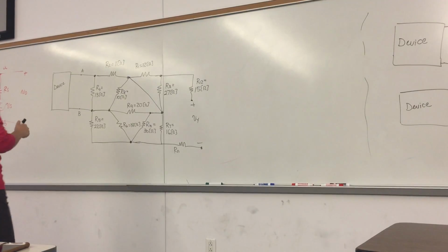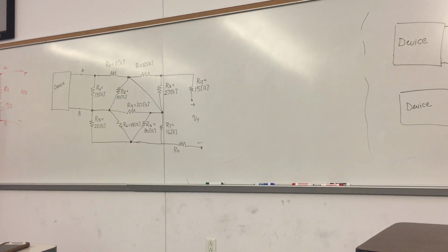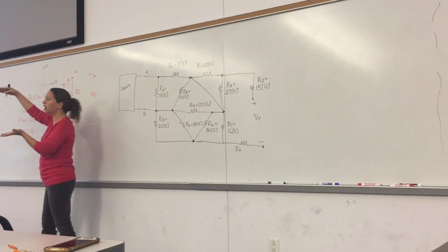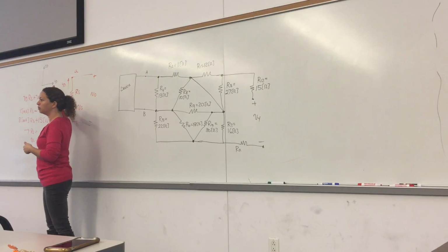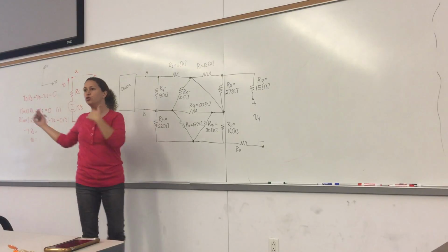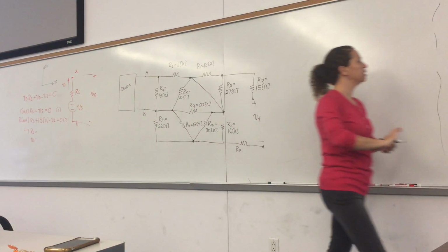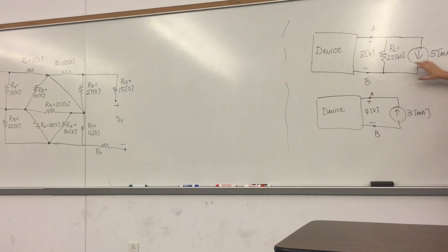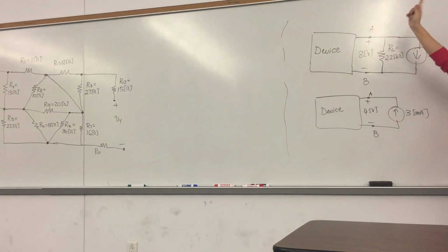Normally in those graphs where you have VD, ID graphs, right? What you generally have is this voltage source, something connected, and then you're reading the ID, right? In that case, I didn't do that, but what I did was I connected a resistor in parallel with this current source, and I measured the voltage. That's my first measurement, first experiment. Okay? So we're going to write an equation from this data.